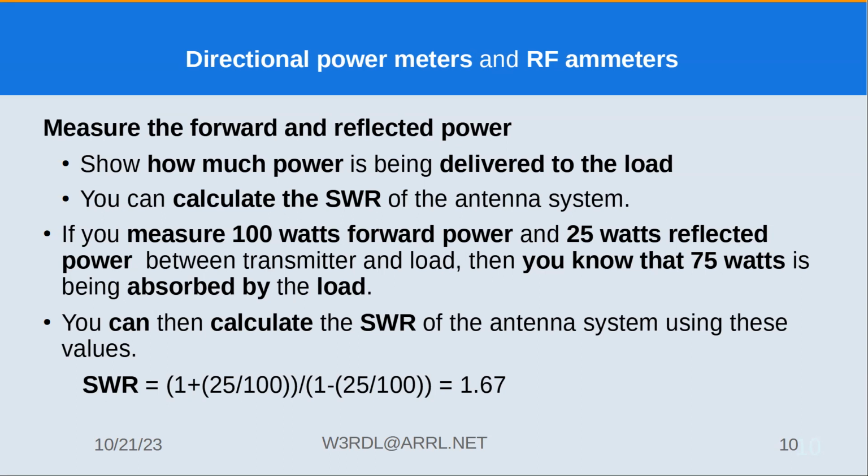Remember we talked about the ratio of ohmic resistance and radiation resistance? If you have a high ohmic resistance, that's all loss. It's not being radiated. What's radiated is the current squared times the radiation resistance.